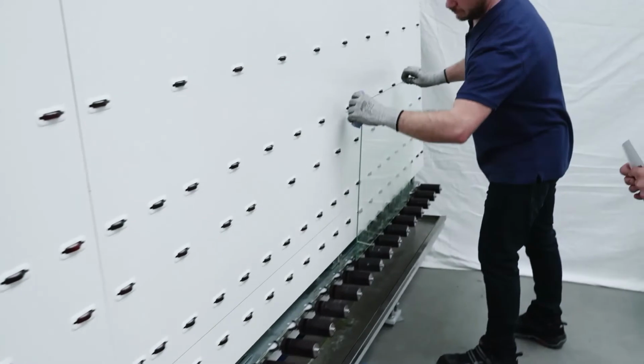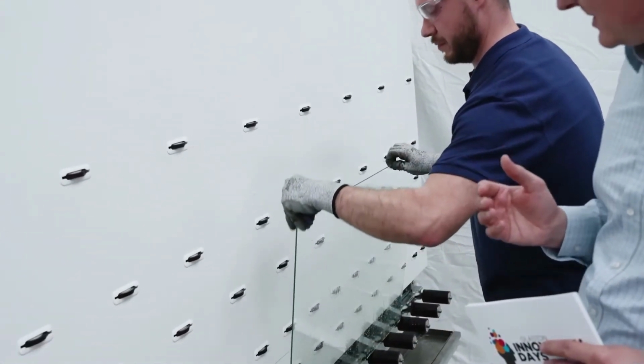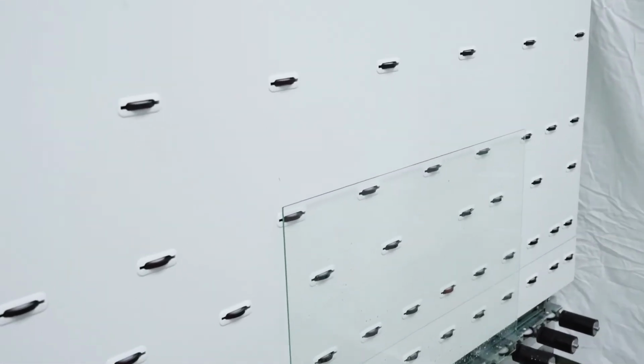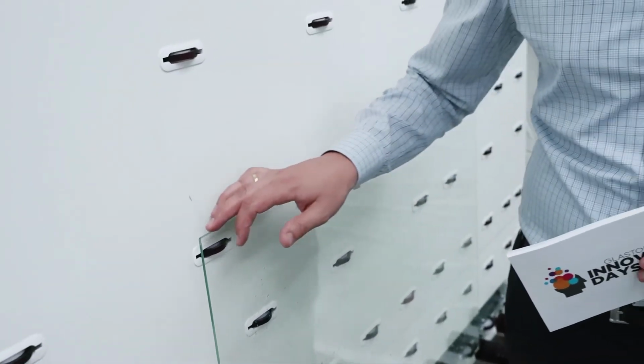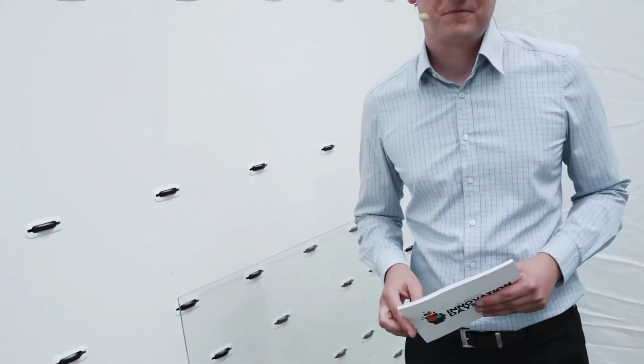We dry the glass with a cloth just to make the arrising quality more visible. And now we see also the flat side is very homogeneous and even, and it looks a little bit frosted, which is typical for the arrising quality. Also the dubbed corners, very nice. So now we have seen in the first run the conventional glass edge arrising. In the second run, the new features. And in the next run, we would like to show you the complete process.